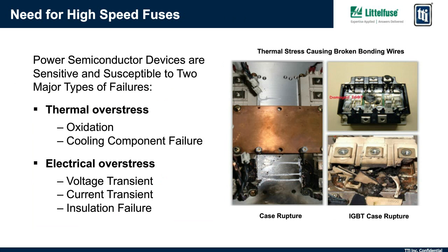Why they do need protection is because, in general, power semiconductor devices are very sensitive and they're susceptible to 2 types of failures. They combine high power handling and fast switching capability in a small package size. With that, these devices generate excessive heat during their normal operation and have low thermal withstand capacity. Additionally, any reduction in size impacts the device's ability to withstand overcurrent and overvoltage. This causes the device to require additional arrangements such as a heat sink and/or forced air or liquid cooling to dissipate the heat and help them run cool.